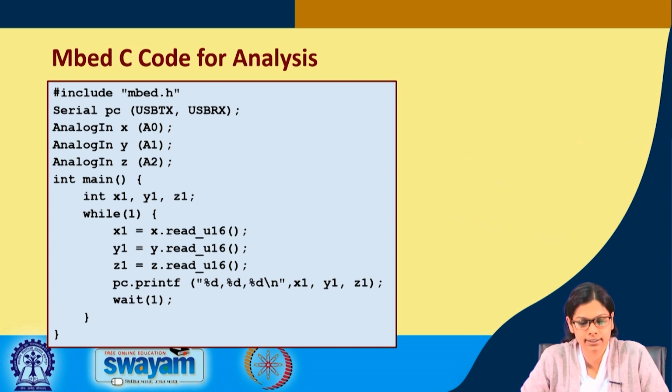So, X out, Y out and Z out will be connected to the Arduino compatible pins of the STM, which are A0, A1 and A2.